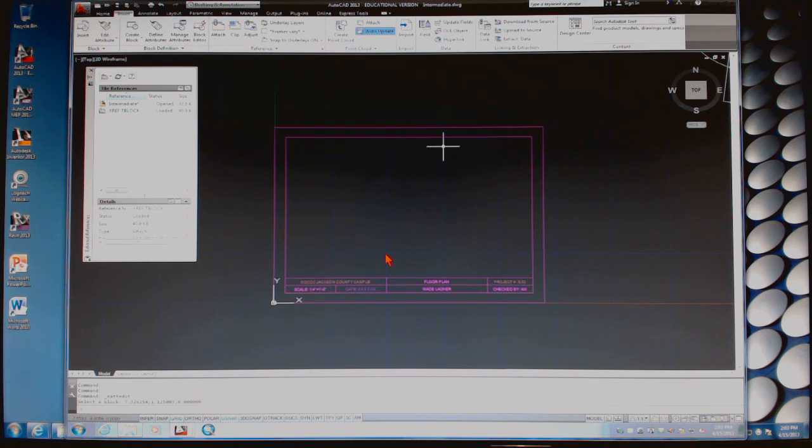There's a way inside AutoCAD called Design Center that you can actually go to drawings that you've previously completed and actually drag the line type in your new drawing without having to create it. You can drag layers in. You can drag dimension styles in, multi-layer styles, blocks. Any of it can be dragged from one drawing to another. And let me show you how that's done.